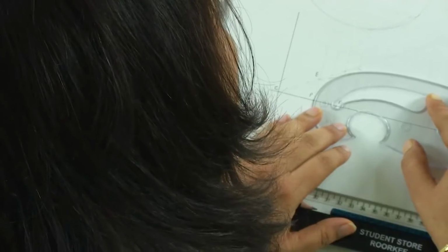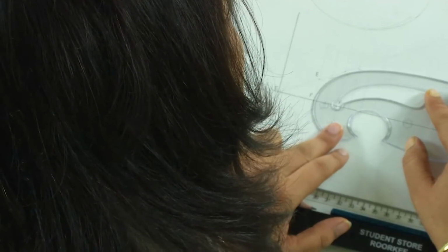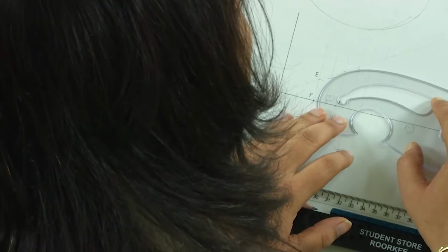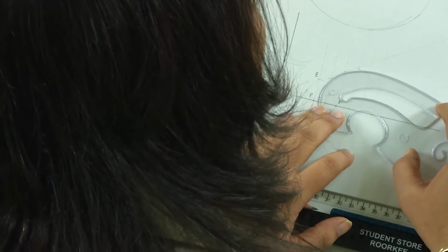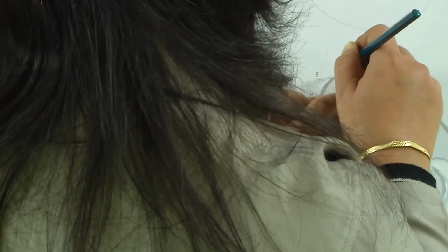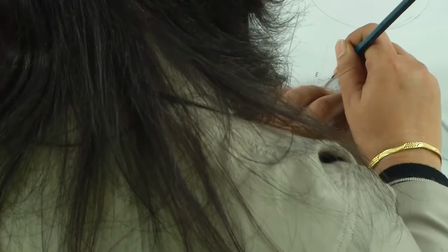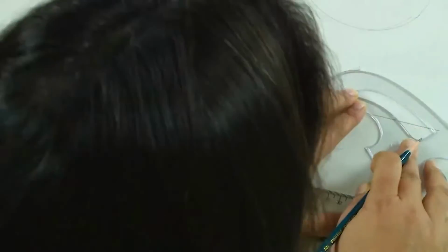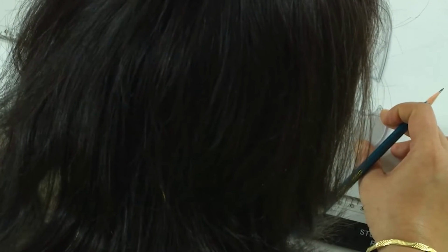So what we need to do is, we need to fix the curve in such a manner that it passes through any three given points. And then we can keep fixing the curves such that the 3 points are being matched. So if you look at it here, I'll draw it very lightly. The curves have to be drawn very lightly. The same curve will be used on the other side always of the ellipse. So you don't need to find another curve to fit this.